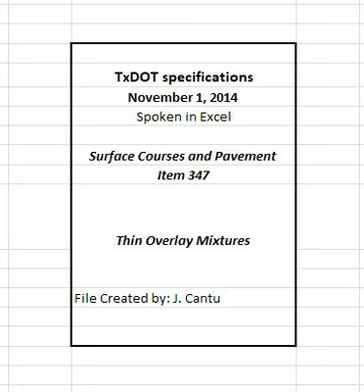4.7.3.3 Hauling equipment. Use belly dumps, live bottom, or end dump trucks to haul and transfer mixture. End dump trucks are only allowed when used in conjunction with an MTD with remixing capability unless otherwise allowed. 4.7.3.4 Screed heaters. Turn off screed heaters to prevent overheating of the mat if the paver stops for more than 5 minutes. The engineer may evaluate the suspect area in accordance with Section 347.4.9.3.1.1, Recovered Asphalt Dynamic Shear Rheometer, DSR, if the screed heater remains on for more than 5 minutes while the paver is stopped.